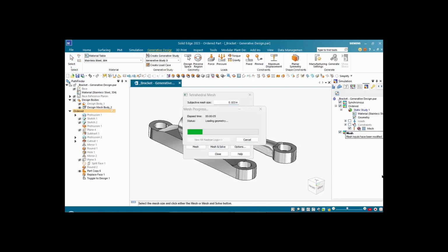Body mesh not only creates cleaner, more efficient mesh, but also eliminates some discrepancies, some sliver faces, in a way that makes the algorithm really very powerful. Now we're going to be able to solve this model and mesh it automatically in one single step. This body mesh, we talked about this before, is a really powerful way of arriving at the results much more quickly than trying to clean up the geometry.